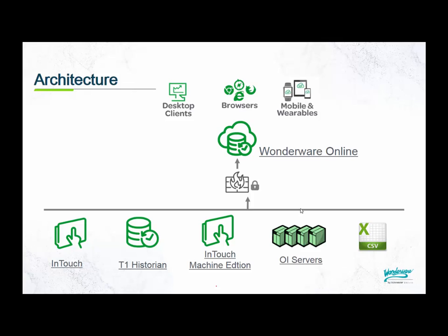Next, we're going to show you how to get data up from InTouch Machine Edition. InTouch Machine Edition is geared toward the panel PCs out there on your plant floor, the local HMIs. Lower cost than a full-blown InTouch application, but we still have the ability to take that data from InTouch Machine Edition and pass that up to Wonderware Online.